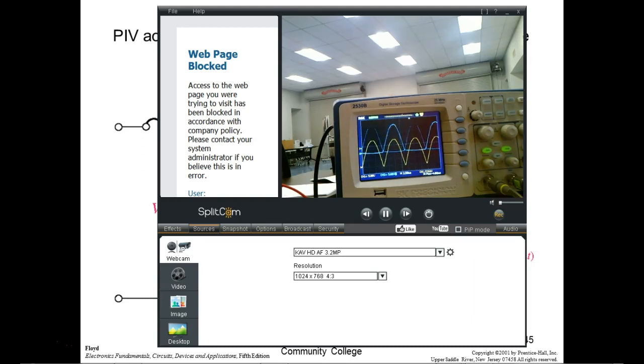What the scope shows you when you're across the diode is when the diode is turned off. Does that make sense? Because when it's turned on, it's only dropping about 7/10 of a volt. See if we can get it to sync. No, we can't. But we can get a good idea.